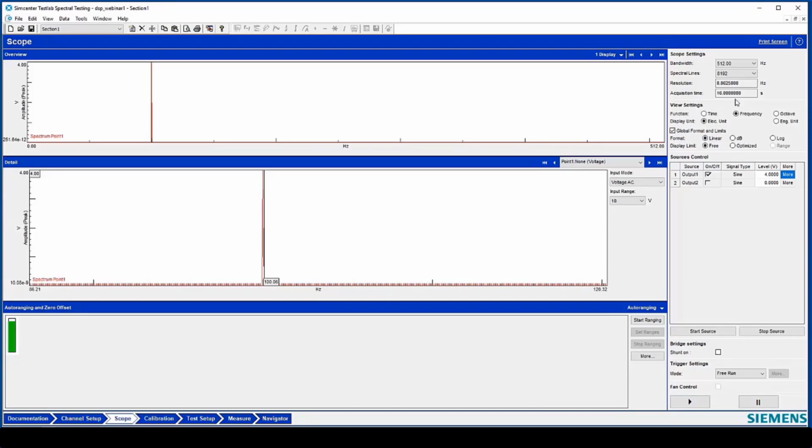Oh, okay. So 16 seconds for a Ferrari, that FFT is going to be kind of, you get a run up, you could get 4 run ups in or something. Yeah, maybe 5. Yeah. So I think you said something like, yeah, you got to be aware of these settings and set it appropriately for what you're trying to measure. If I got a 4-second run up, maybe I want 1 second FFT or a 1/4 second FFT. I'll give up a little frequency resolution to get a little more resolution over versus RPM or time or whatever.